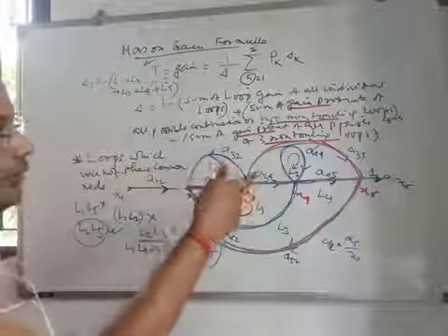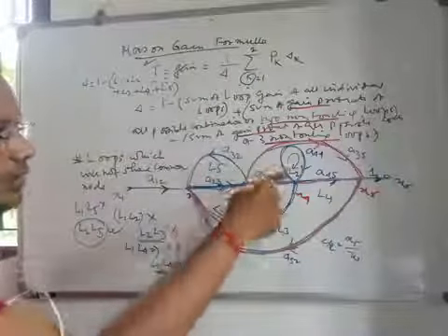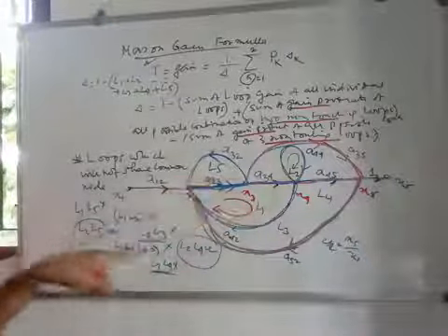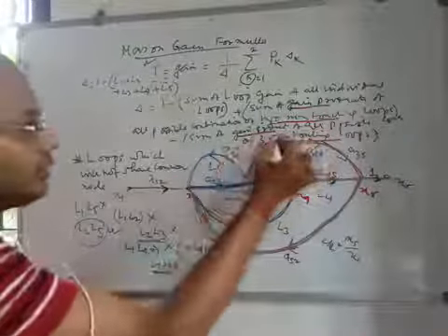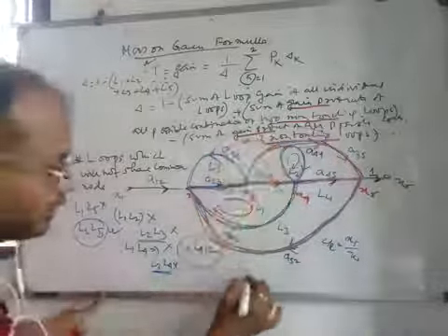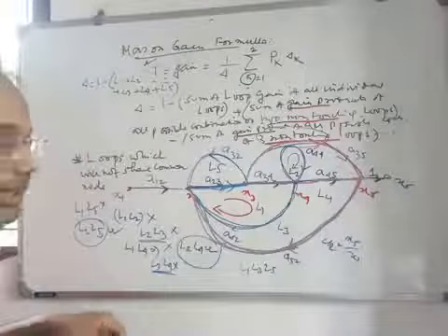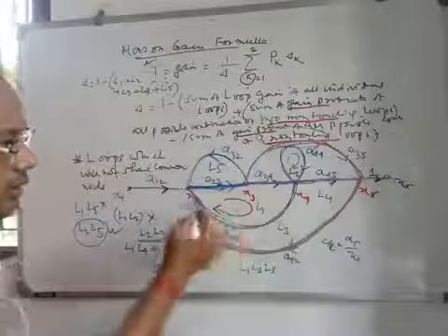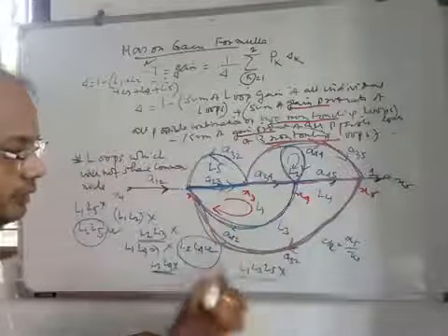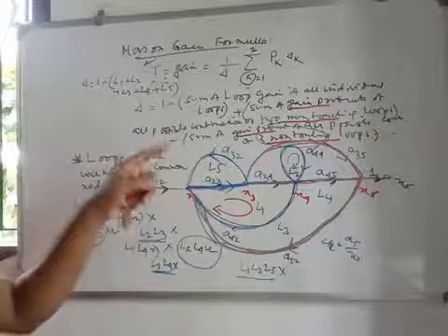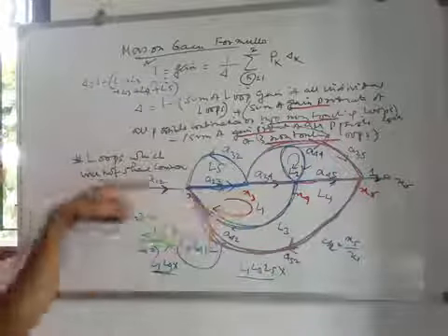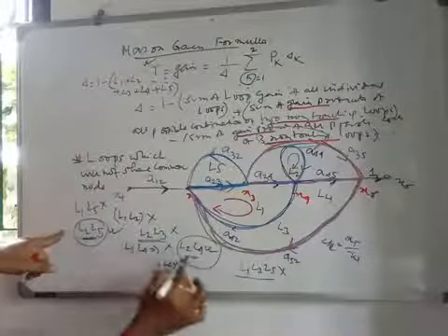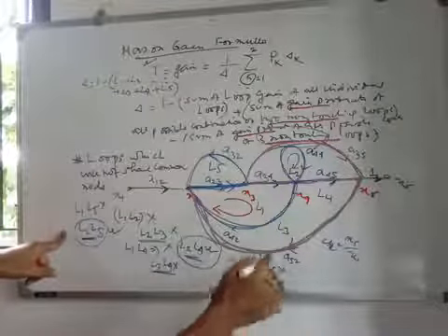Similarly, we check for three non-touching possible combinations: L1, L2, L3, L2, L3, L4, L1, L2, L5, and so on. Here, there is no such combination where three non-touching loops exist. For example, we are considering L1, L3, L5. This is your L1, say this is your L3, and this is L5. They are touching. So by this you have to find out the possible combinations. What are the possible combinations you get now? L2, L5 and L2, L4. So there is no possible combination of three non-touching loops.